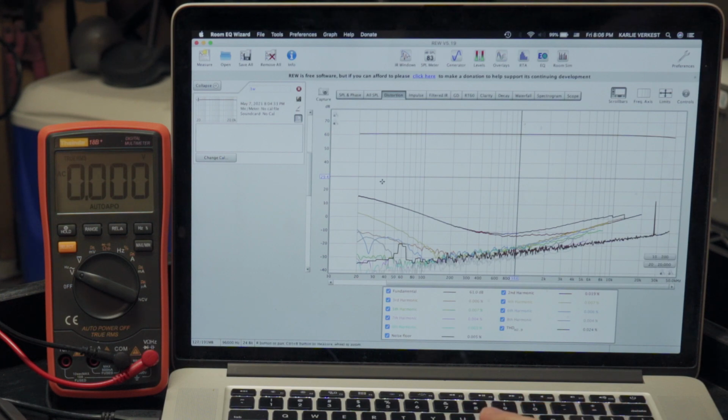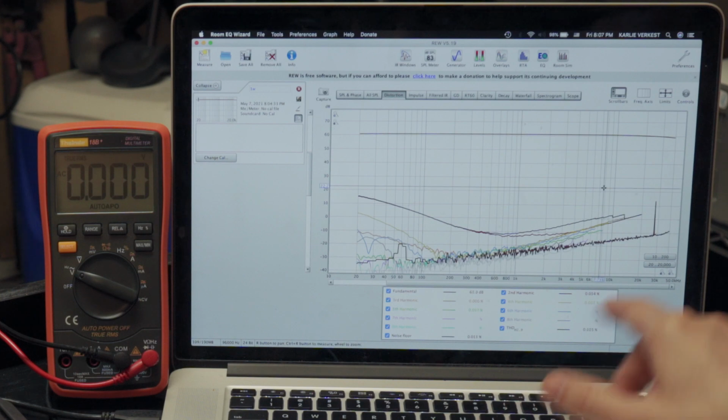But look at this. When we were measuring before, we never would have noticed that there's this rise in distortion up to the low range here. At 30, we're at 0.4, and at 20, we're at 0.53. If you only had a 1K measurement of this amp, you would think that it was a 0.025% distortion amp. But you'd be measuring it at its most optimal frequency, where it generates the lowest, and obviously it's rising up here.